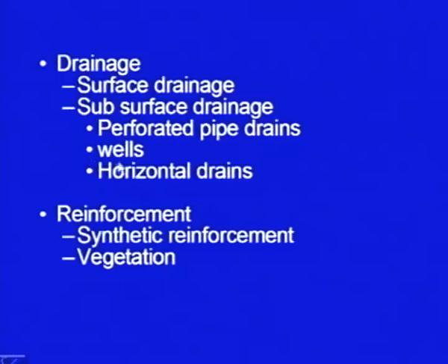Wells can be used; this is a little bit costly affair, so it depends how many resources are available. The water table can be kept under limits, so that it does not rise to a level where it can cause failure. Horizontal drains can also be provided inside the soil mass.